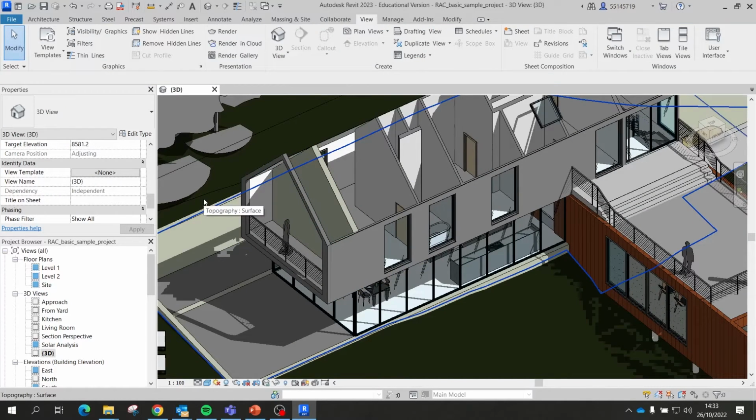And you see, it was done with one click, right? Imagine the amount of information this little click carries. If I had a schedule now, which I can do within the same software, with the exact number of walls, the square meters of that type of wall, the cost for each of them, that schedule would automatically update in another window without you even knowing.